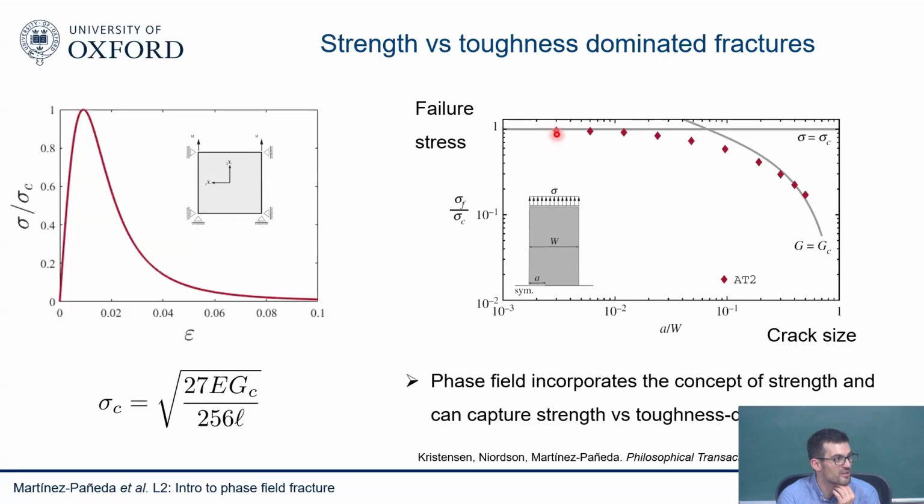When I pick a crack that is very small, my applied load is in agreement with the toughness because you get an almost uniform stress field. When I pick a crack that is long enough, my critical load agrees with the one that will come out of Griffith's energy balance, the fracture mechanics. How you calculate G?